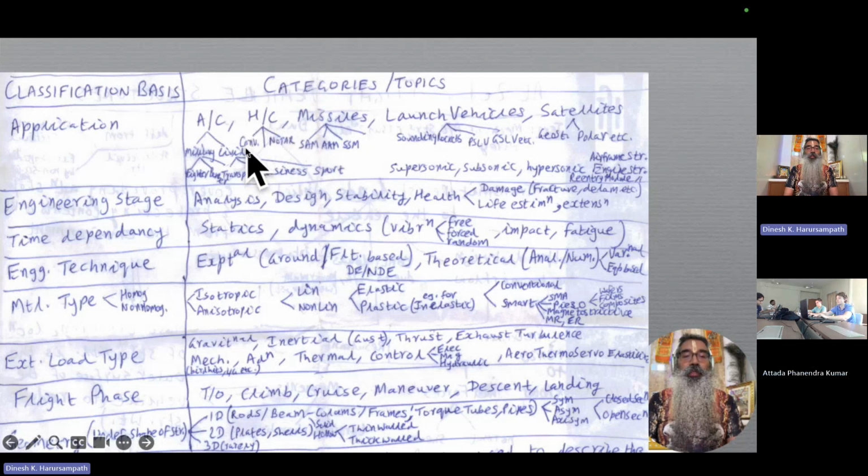So when we look at helicopters, in terms of the structures, there's a huge difference. The main lifting structure in the case of the aircraft is the wing, which is a fixed wing, whereas here you have a rotary wing. And the rotary wing is a much more complicated, complex animal to deal with from all points of view, including structures. From the structural point of view, what we are looking at is a much larger axial load compared to an aircraft, because an aircraft's wing can, for all practical purposes, be modeled as, let's say, a cantilever beam to start with, and then of course we can introduce further complications to it. But the simplest way is to model it as a cantilever beam.